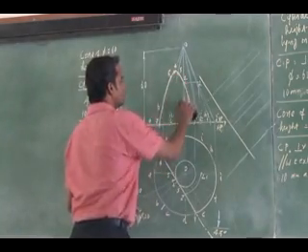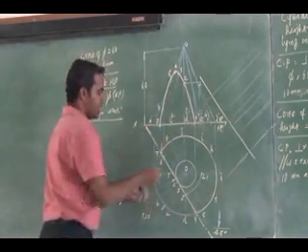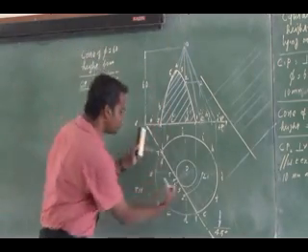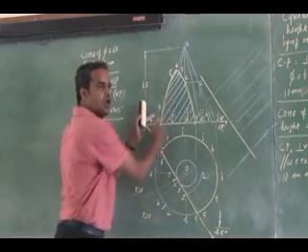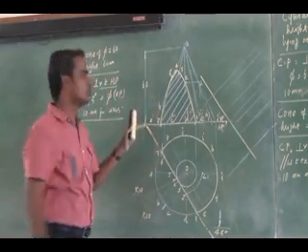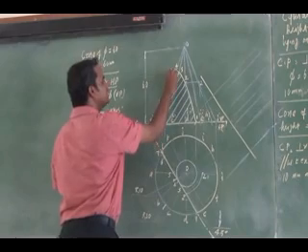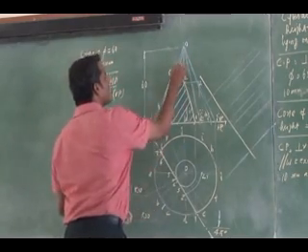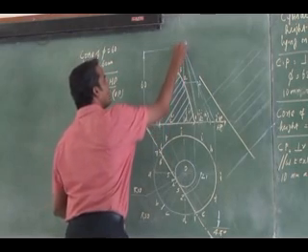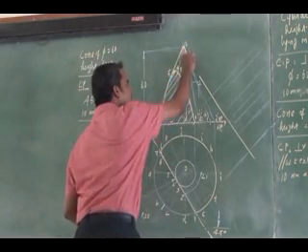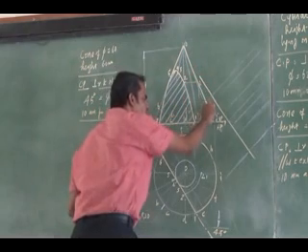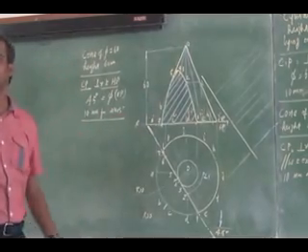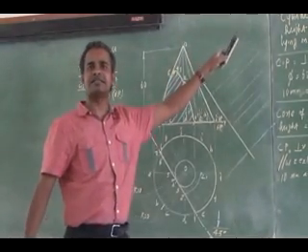This is the apparent section. Then the retained front view has to be darkened. So this portion is removed. I cannot see this portion of my front view cone. Then the retained portion is tangent to this. So a triangle will be seen in my front view. So this is my retained sectional front view. Then you can go for your apparent section.